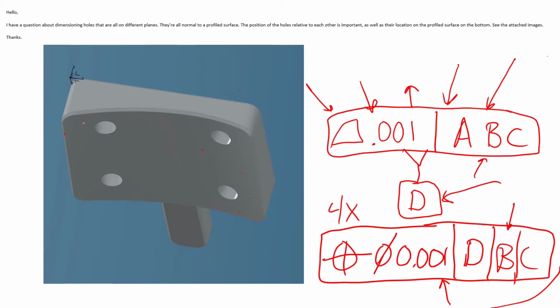But now here's where the tricky thing comes in for the inspector. The inspector now needs to somehow, in their CMM or virtually in some way, you really can't do this using gauge blocks and things like that. The previous example, you might be able to use gauge blocks to set up your datums. In this case, you need to set up that, remember we said that it was 50 inches away. You would need to somehow set up this axis.